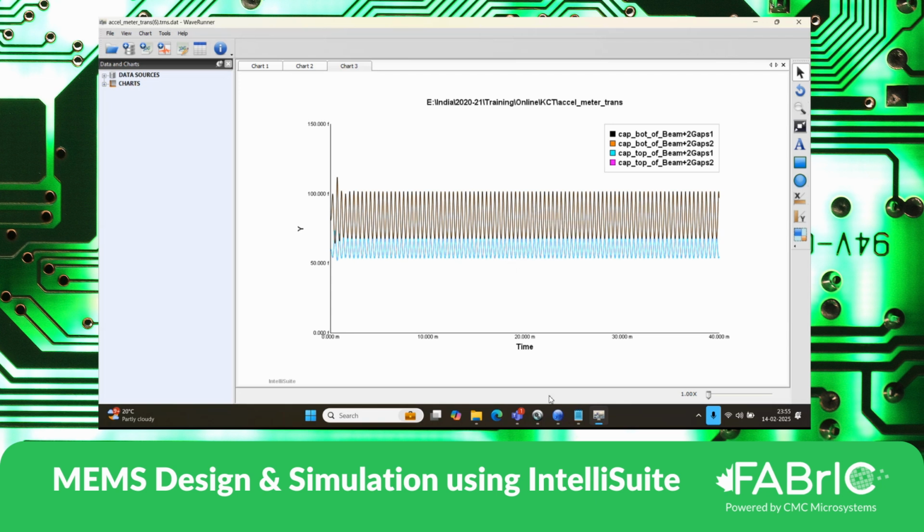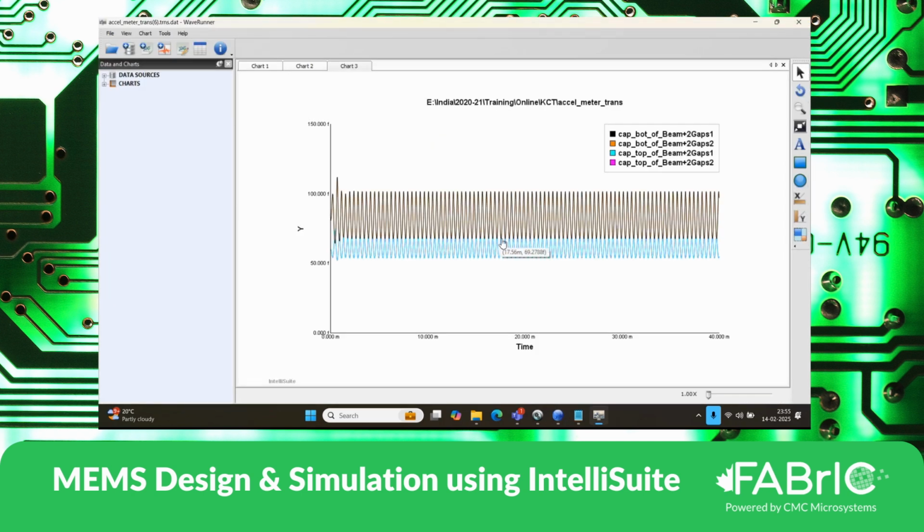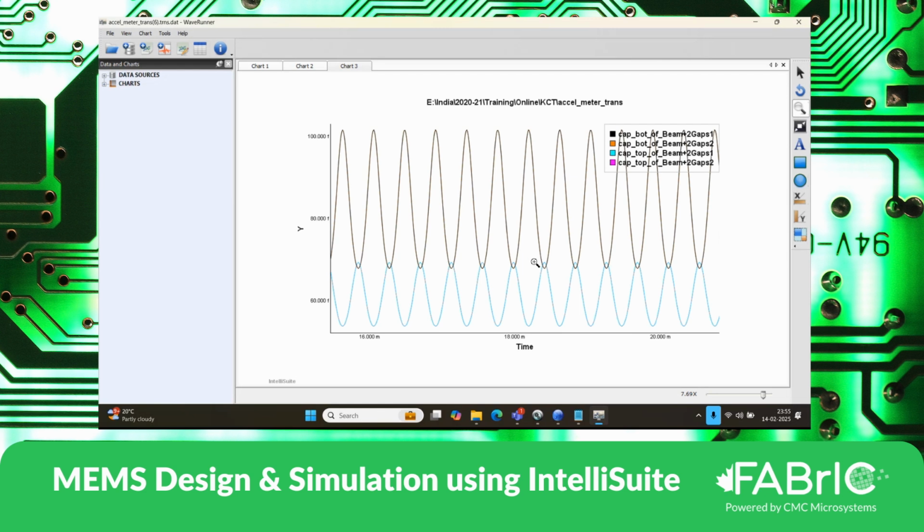Whenever there is a deformation on the right side of the accelerometer, the capacitance on the left is less because the overlapping area is low. In the same way, when the left side is pulled, the capacitance on the right is low because the overlapping area reduces. So there is always a balance that happens with respect to time. This is the overall capacitance that we have right now. If we zoom in here, this is what we have.